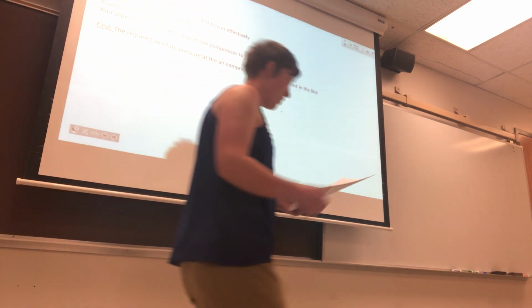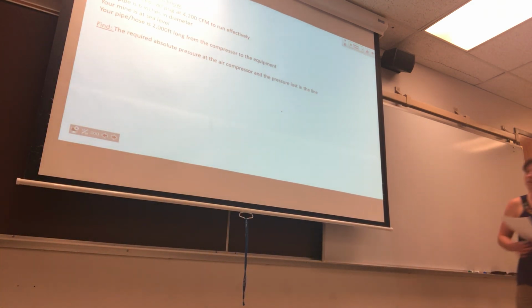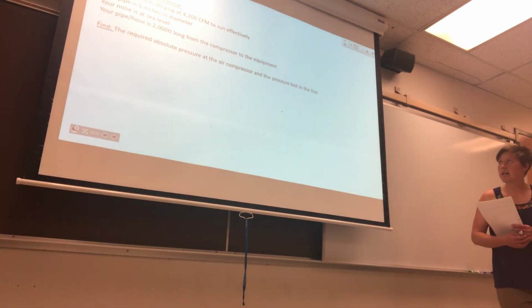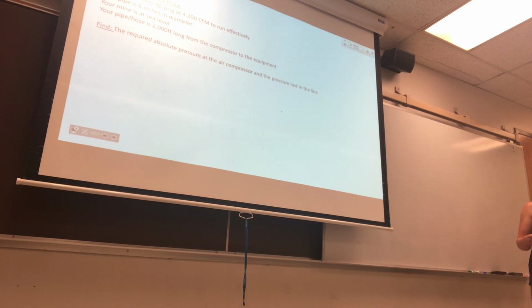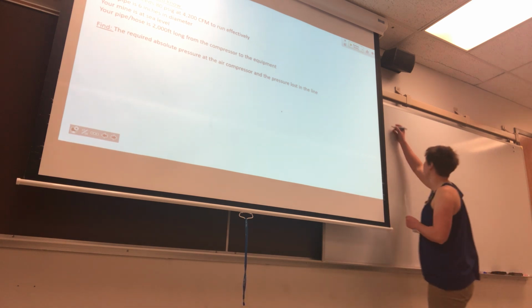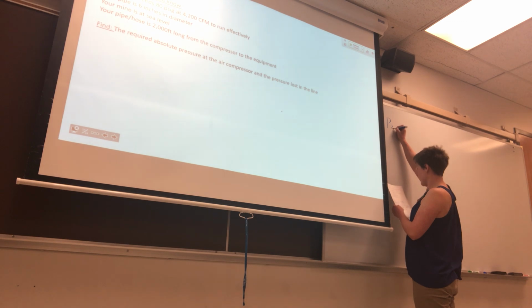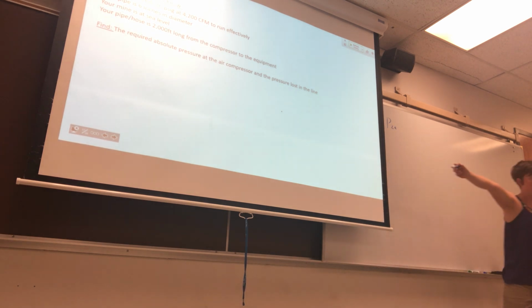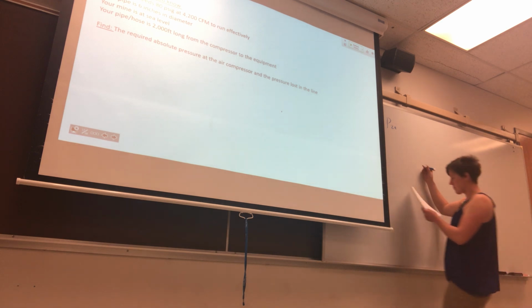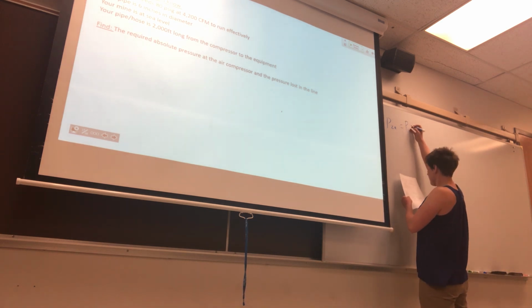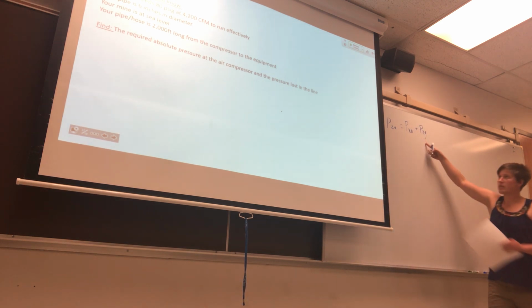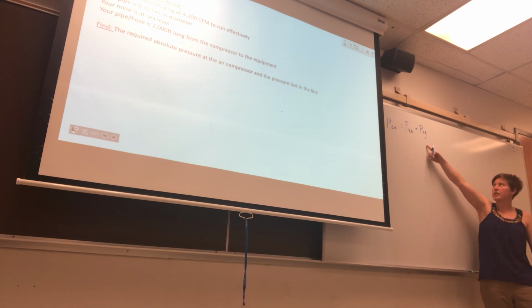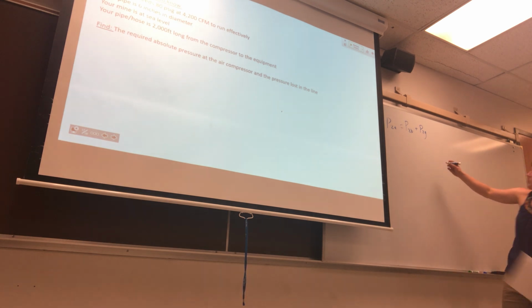Alrighty, let's go through this problem here. Okay, so our equipment needs 80 psi G, so we're reading that at our equipment. We need to always translate to the absolute pressures for our line losses, so let's start with that. So we'll say the pressure, we're gonna say that's 2 because that's further, at our equipment down the line. Okay, that's the absolute is going to be the barometric plus that gauge pressure. So we know what the gauge pressure we need our equipment to work at. So that's that 80 psi G.